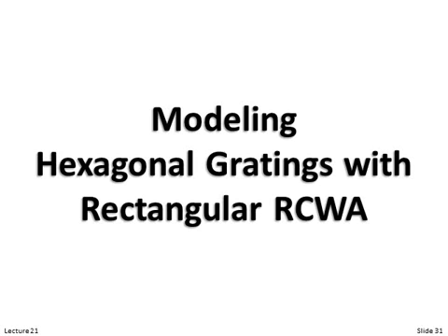The last topic is modeling a hexagonal grating with a rectangular RCWA. Hexagonal gratings are advantageous from a number of perspectives, but one thing is you can get away with larger feature sizes in a hexagonal array than you could in a square array for operating still at the same frequency or wavelength. And so particularly for optical devices, when you're building things at the micro scale, we tend to like to build larger features because it's hard to make those smaller. So hexagonal arrays are beneficial from that perspective.